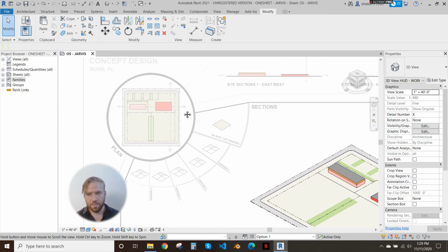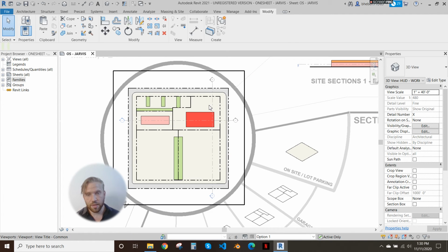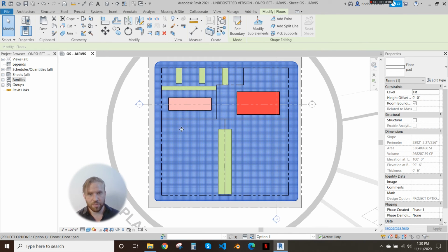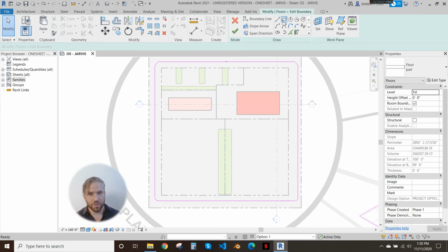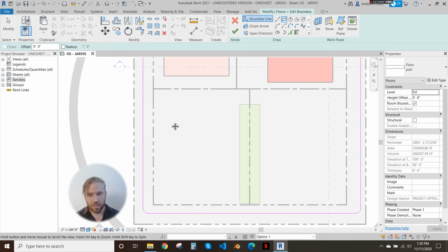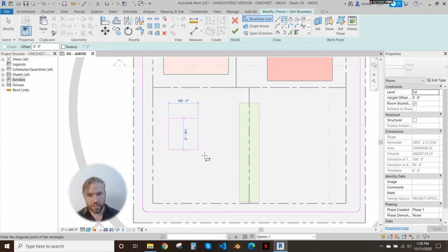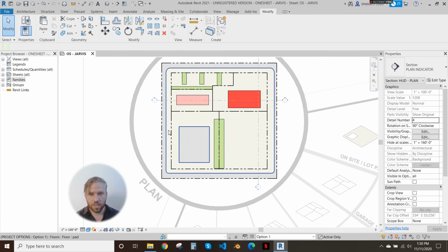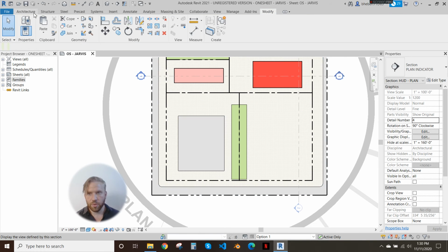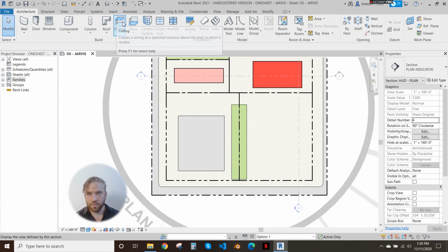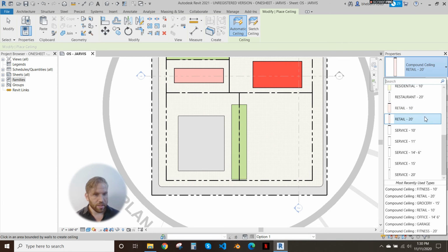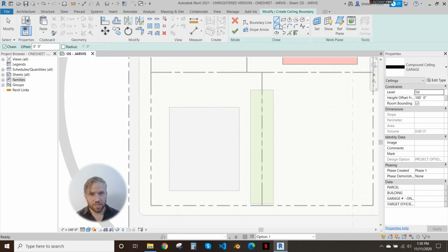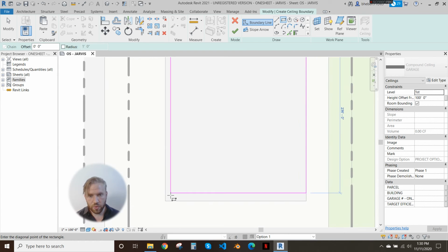The next step is I want to start drawing some parking, so some garage, not parking, but just some garage, right? So if I select my curb here, my first floor for a garage, I'm going to edit boundary, needs to be on the same plane as the level one. So I need to actually cut a hole in this building pad, this curb, and I'm just going to say that is my garage. Okay, and then I'm going to go architecture. I'm going to go ceiling, and I'm going to come down here to garage. And there's only one because this is really just a plane. Let me sketch this, and I'm just going to go over this same line.